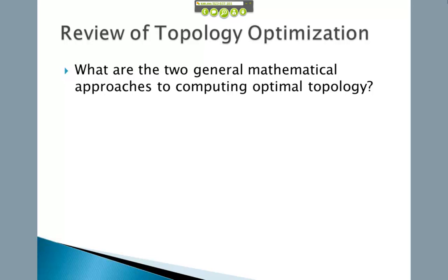How does that work? You change the size of the void and therefore the density of the material. Right, so if we think of the void as being rectangular, which it doesn't have to be, we can vary the length and width of that void in 2 dimensions. And by doing that, we change the density of the cell, the density of that finite element, and compute the load paths, the stresses and strains in that type of an element.